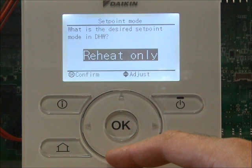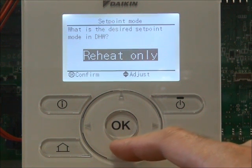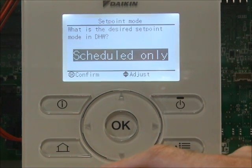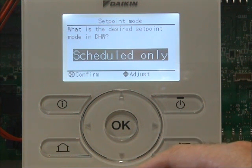Reheat only. It's not doing a schedule, so if you have reheat only, it won't allow you to select a scheduled time for it. And you've got scheduled only. If you want controlled heating of the hot water, you can set it to scheduled only, and that will actually control the times at which your hot water will be heated. For example, 6 o'clock in the morning, or 5 or 4 o'clock in the morning, and 3, 2 or 1 o'clock in the afternoon.